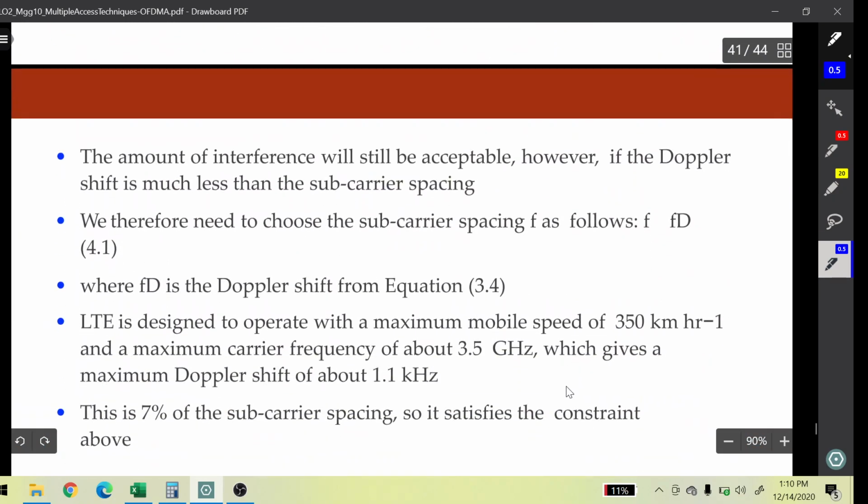Now, thus deciding the frequency spacing is very important. In the LTE system, we design to operate with a maximum mobile speed of 350 kilometers per hour, and a maximum carrier frequency of about 3.5 gigahertz, which gives a maximum Doppler shift of about 1.1 kilohertz.